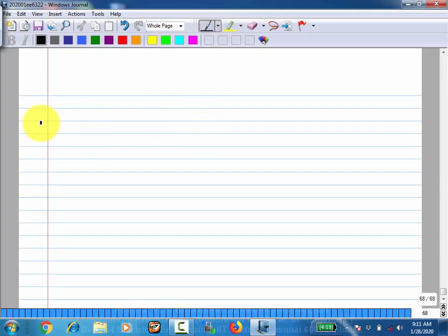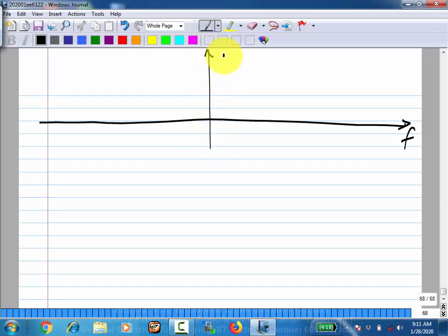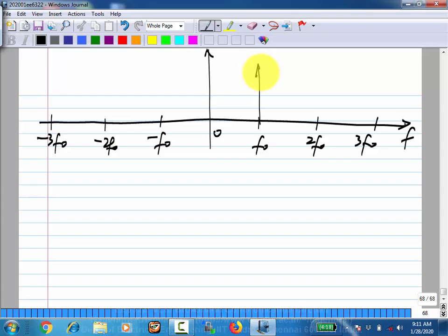So now you can write the spectrum of the jittery clock like this. It is the original clock plus the error signal, right? The original clock in a two-sided spectral density, it would have these. If it's one-sided, everything gets doubled, nothing changes, right? So what was the strength of this again? 4Vp square by pi square. Okay, and this was 4Vp square by 9 pi square and so on.